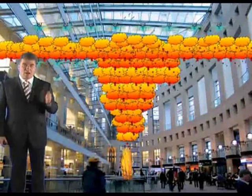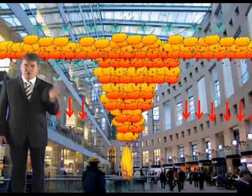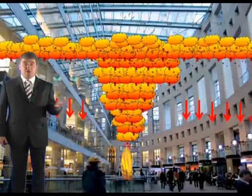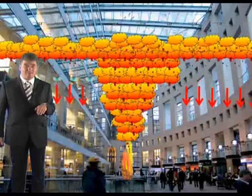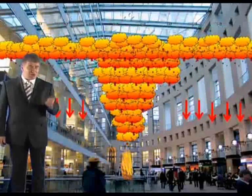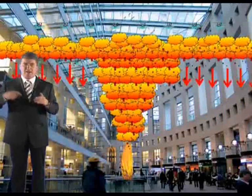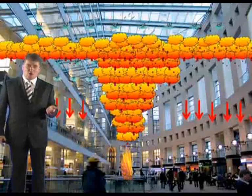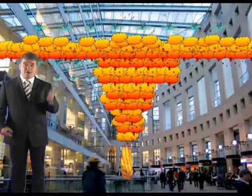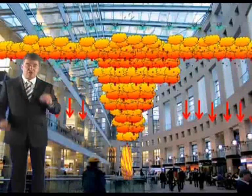It should still get out. It shouldn't affect it. When the fire occurs in a shop, the operation of the sprinklers in the mall will not assist in controlling it. So the sprinklers going off in the mall are not going to help a fire in the shop. That's why you need them in the shop as well. Now the problem is, if too many sprinklers operate in the atrium itself, sprinklers in the shops become less effective because it's about flow rate as the available water supply approaches its limits. So if a lot go off in the mall, it's going to cause a problem in the shop itself.